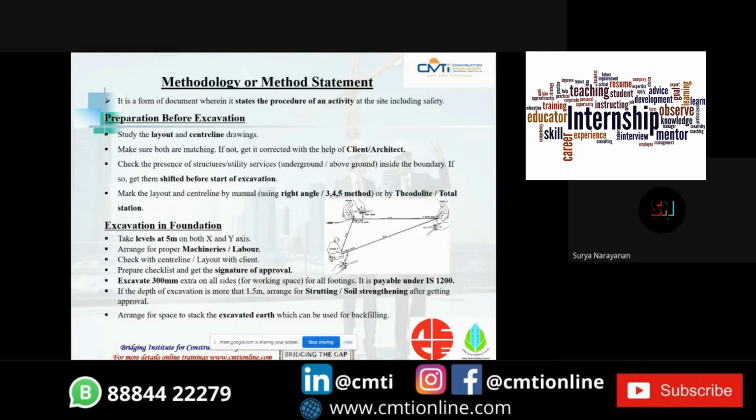So during excavation and foundation, we should always take 5 meter levels on both x and y axis, and also arrange for proper machineries and labors. We should check the center line or layout with clients. We should prepare a checklist and get its signature of approval. And we should also excavate about 300 mm extra on all the sides for working space, which is payable under IS 1200. We should also arrange a space for excavated earth, which can be used for backfilling in the construction itself.